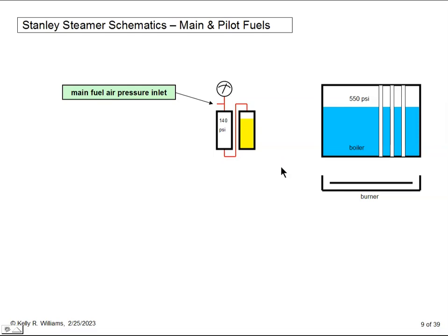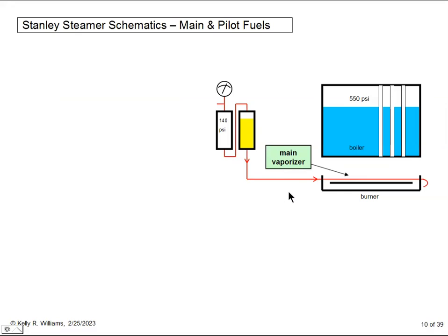So now we let the fuel out of the pressure tank and send it right across the flames of the burner to be converted to a vapor. The vapor is shot into the underside of the burner at high speed, mixing with air, and then burning above the grate. If you're thinking ahead, you might wonder how to get your first kerosene vapor in the morning when all the parts of the car are stone cold. That requires the magical bootstrapping process called firing up. Those details are outside the scope of this presentation, but we will touch on that a little bit later on.